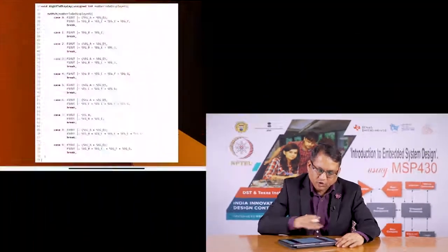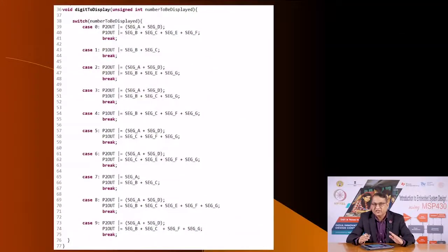And this count is what is to be displayed on the digits, and so this count must be a variable which is of the type volatile. And so, I strongly recommend to you that based on this discussion, based on this description of how the code is designed, you go through this code. The code has been nicely partitioned into several subroutines and 2 interrupt subroutines, and a main code in which the switch is being looked at and the count incremented based on that.